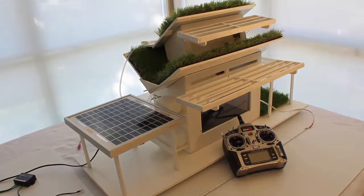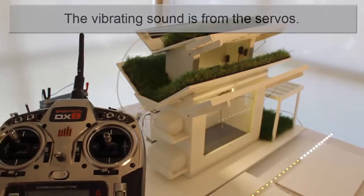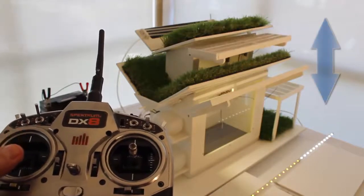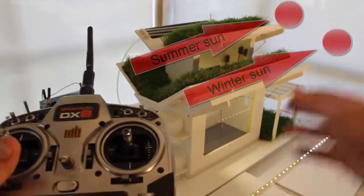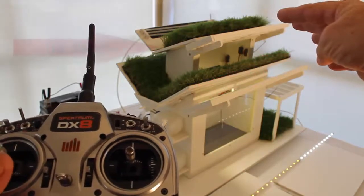This model communicates with a transmitter, a typical remote control transmitter used for model aircraft. The transmitter would move the louvers. We've powered the house. The receiver is communicating with the transmitter. So the first thing I'd like to show is the louver on the clerestory moves up and down. So the sun sits higher in the sky during summer and lower in winter. So if I lift it up, the sun, which sits over here somewhere, would shine through the window and heat up the stack.